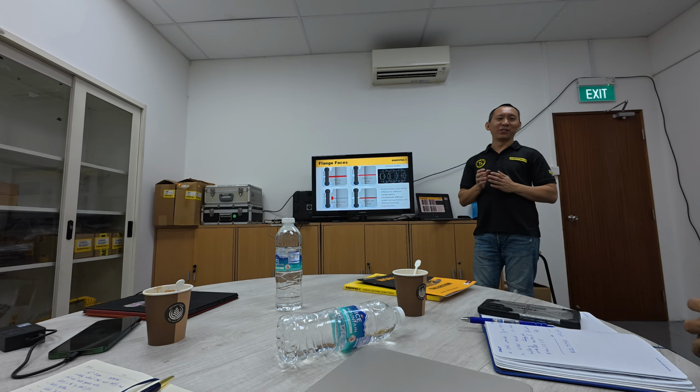Okay. So we have also things like clamp connectors, the 4-bolt 2-piece clamp connector in the market. For this type, dogging will be preferred due to the 2 feet, usually with dogging, and of course flexibility and time concern. So the method, whether it's dogging or tensioning, a lot depends on what type of connection is on the joint.